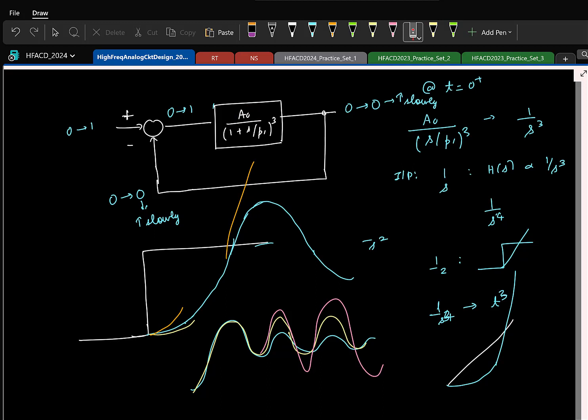That is like saying, in the water analogy, you increase the inflow and outflow of the water, right? You sense temperature, then you increase the hot water more, so the temperature will increase even faster, right? So bottom line, if you have LHP poles, it introduces time delay, and anytime you have a delay in any kind of feedback loop, that can result in instability.